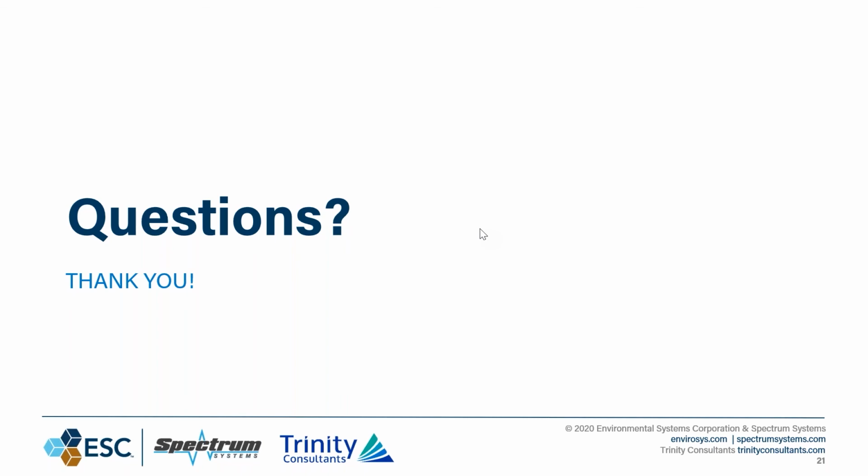And for those of you that are keeping strictly an electronic version of a log on the server, I'm going to caveat it with this. Your ability to retain that information is only as good as your last backup. So if it is being stored within your DAS, it is my sincere hope that you're doing routine backups on that server on a very regular basis. My former employer, we were doing full server backups once a week and differential backups every day for all of our systems, all of our DAS servers.